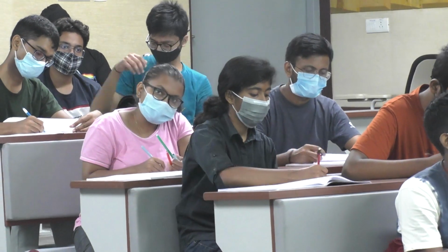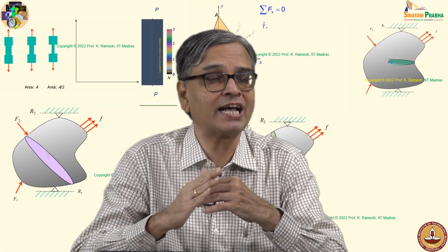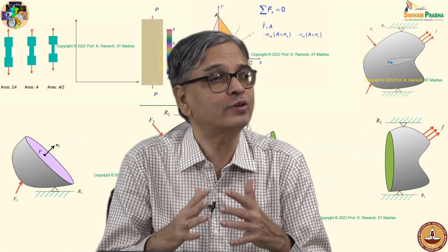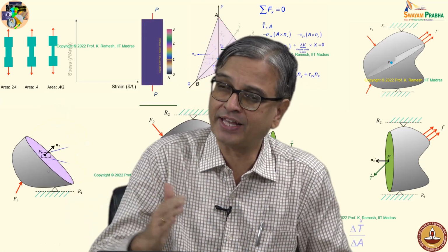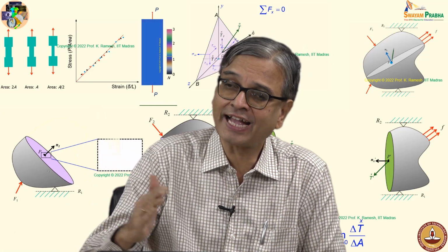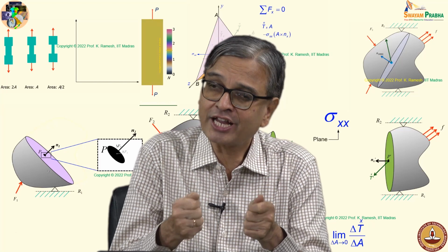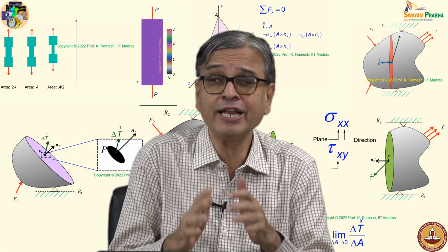This is a very nice mathematical advantage when you want to solve a problem from a mathematical perspective. So, as long as you apply a statically equivalent system, you can conjecture the similar distribution is achieved at distances away. And this distance can reduce if I make my application of the force system closer to what is intended for. It's a very powerful tool.